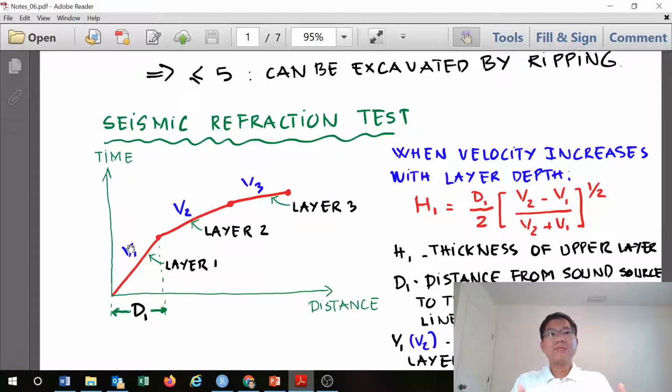Okay, so generally it ranges, the seismic wave velocity in soft soils is about 1,000 feet per second, up to, for hard rock, 20,000 feet per second. And that difference here, we can measure if we have different layers, different types of soil, different types of rock. Normally, as the layers go down, they tend to have higher density, and that implies the velocity tends to increase.